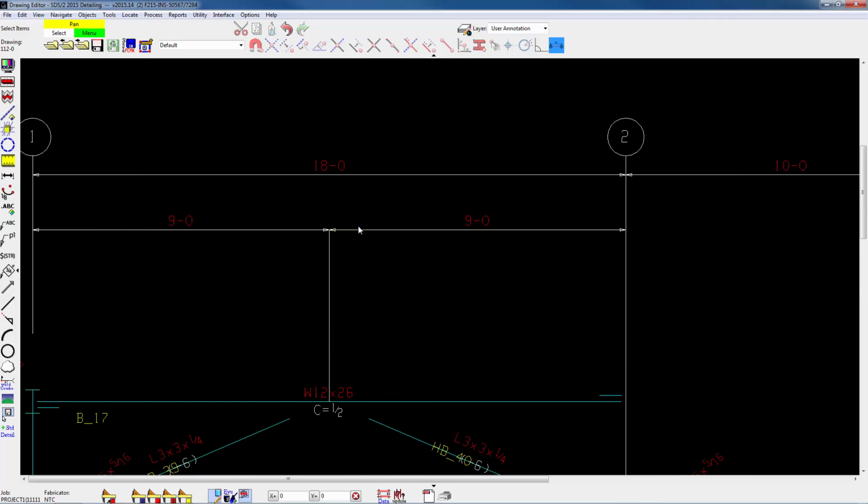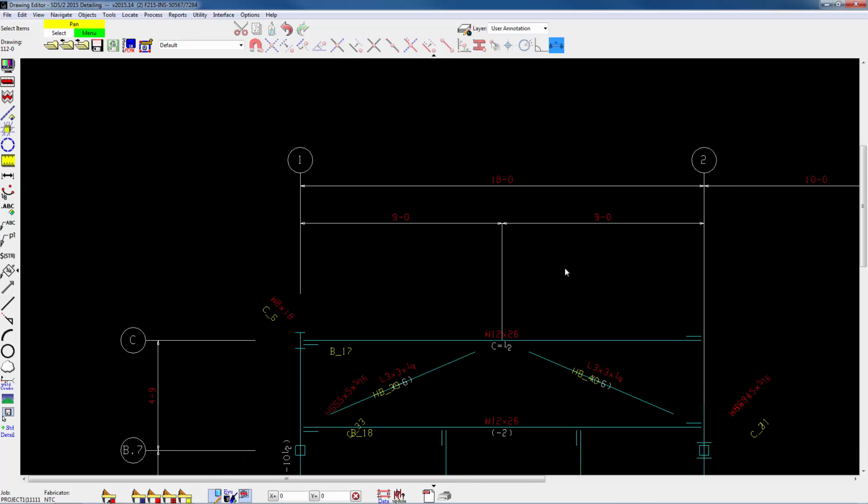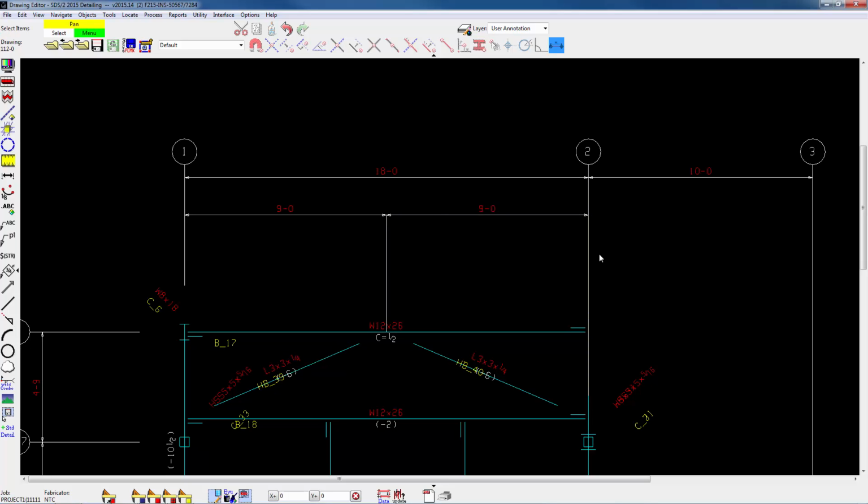Now one thing I will note on the dimensioning is if you look at your plan views, the dimension lines are cut off about here, and then from there into about here is shown as a center line, and it's a really light line, so it differentiates between a dimension line and a member. Again, preference, I prefer the dimension lines to stop out here and then the center line continuing in. So one option to do that.